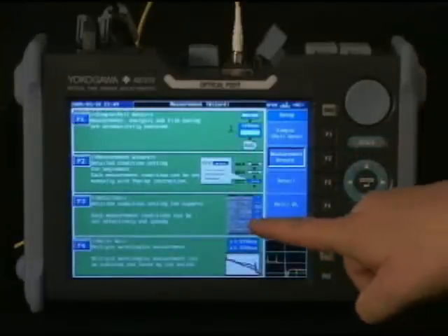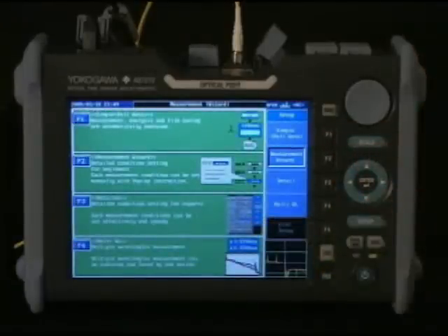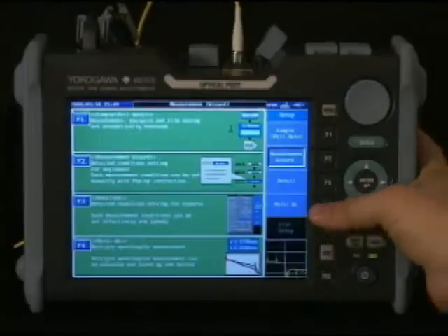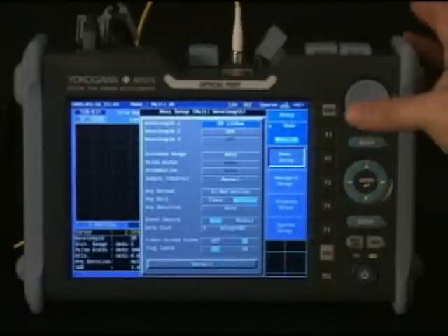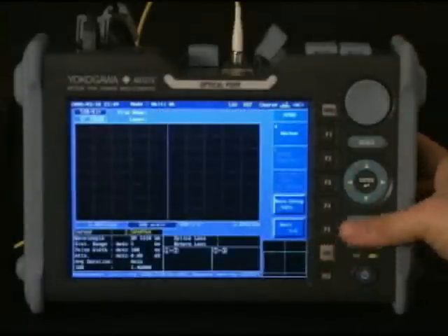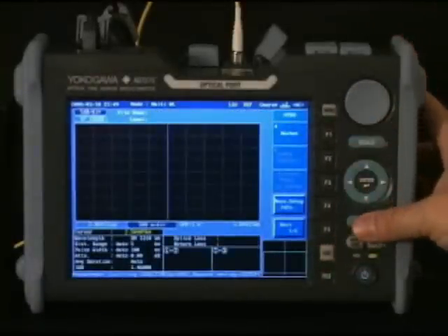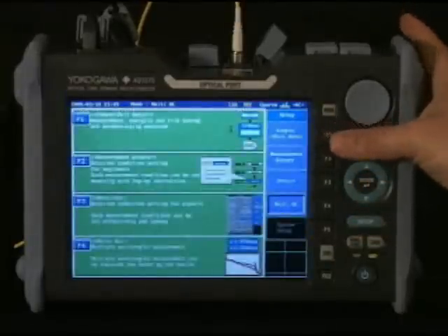The Detail mode is very similar to the Measurement Wizard, but without the explanations. There are also some extra definitions that can be set, like the Display Setup page and Power Save modes. Finally, there is the Multiple Wavelength Setup page. We've completed a simple full auto test and have seen the optional setup page of the AQ7275.